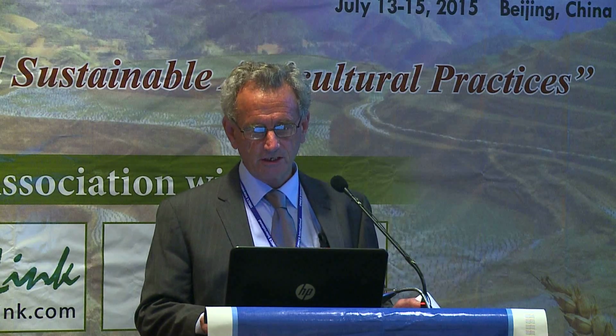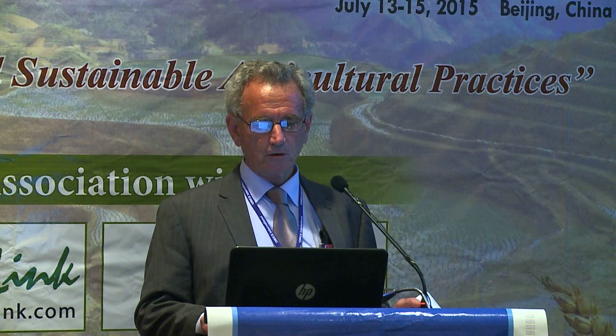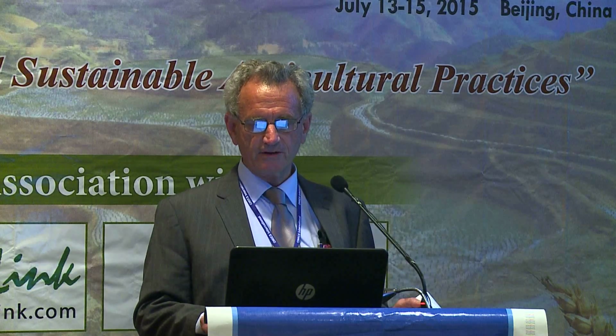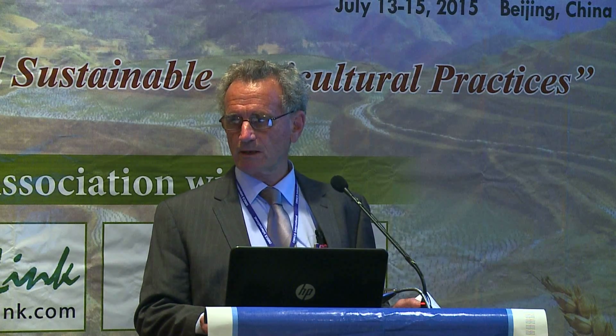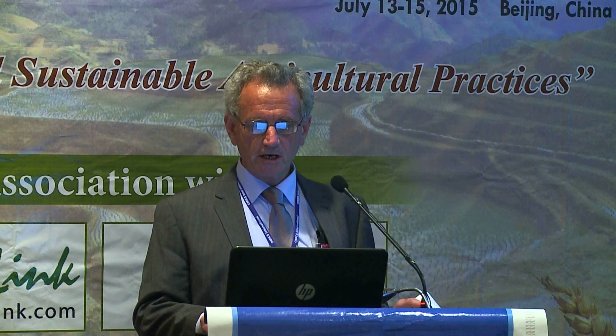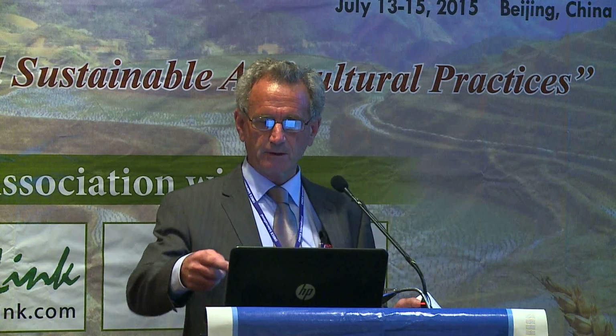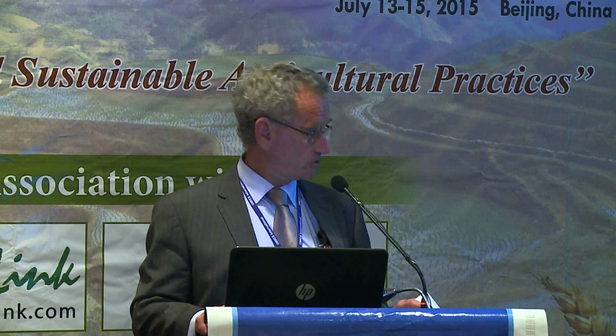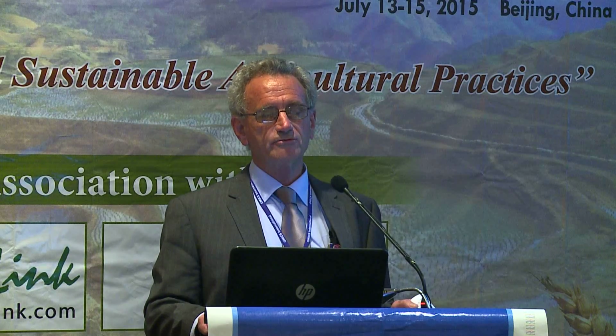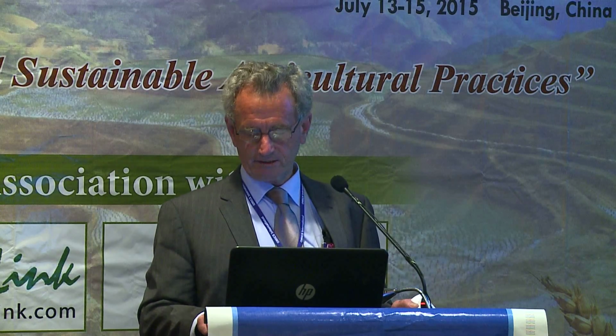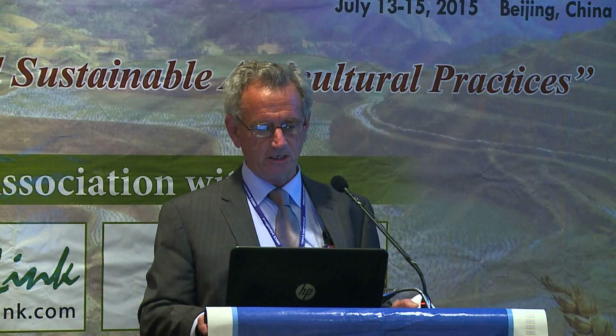Now, I just should emphasise at this point, we're not using evaporation to decide how much water each plant gets. We decide how much water each plant gets by step 1, by choosing the required application rate during the hottest dry month. But then, once we've chosen that figure, we allow the application rate to vary throughout the year according to the net evaporation at the various times in the year.